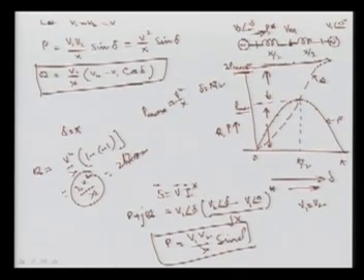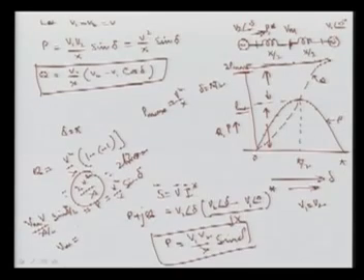To see this, the midpoint voltage can be calculated here. The power flowing over this section will be equal to the power over this section. Means I can write here, this is your Vm, V upon x by 2 sine delta by 2 will be equal to P, or this P which is flowing here, I can say V square upon x sine delta. Means I can write this Vm will be nothing but your V cos delta by 2.